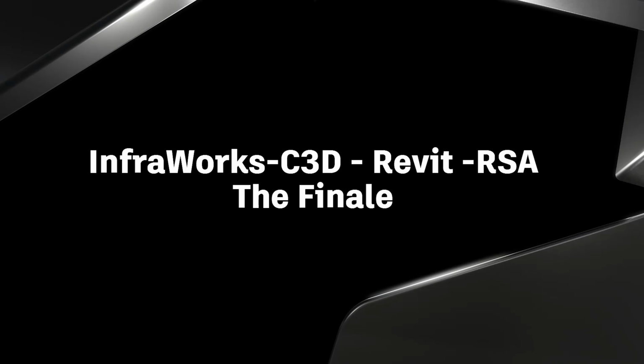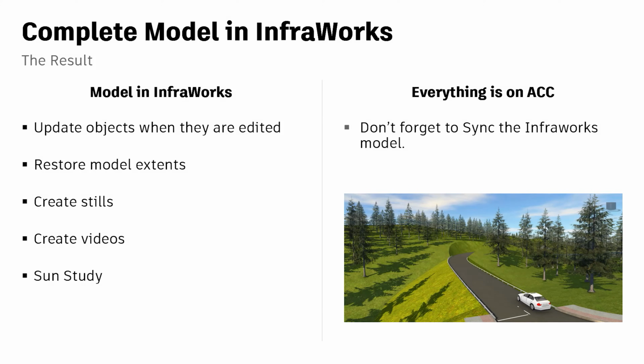Thanks, Hung. So to finish off our class today, just a few cleanup items. Number one, you're going to update objects as they're edited: AutoCAD drawings, Revit models, GIS data sources if they've changed. Go into your data sources panel in InfraWorks and update. Now, for this model, for performance reasons, I've limited the model extents. In a moment, I'll restore those extents so we can see the entire thing. You want to do that before you create your stills and videos and sun studies. But I'll do the stills and videos first.